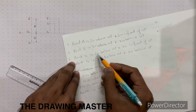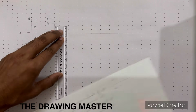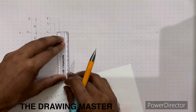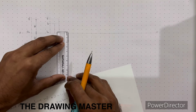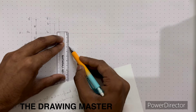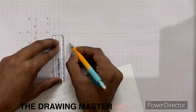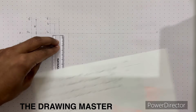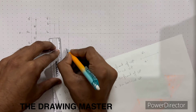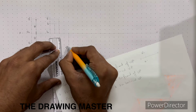Third problem, point C is 30 below HP and 20 in front of VP. So let's see here. 30 below. Below HP means below the reference line. Above means above the reference line and below means below the reference line. Thin projection line. This line should be thin. The name of the point is C, 30 below HP. So below means below the reference line and it is also front view. Lowercase letter with dash.